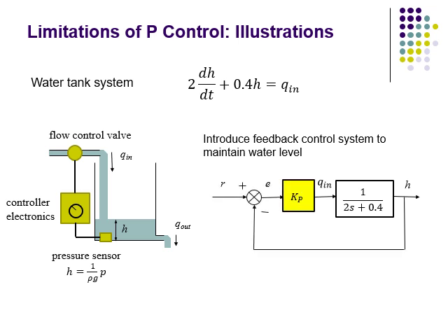So if we put these three components together, the sensor, the controller, and the valve, then we can create a simple model which gives us the feedback structure shown in the block diagram.